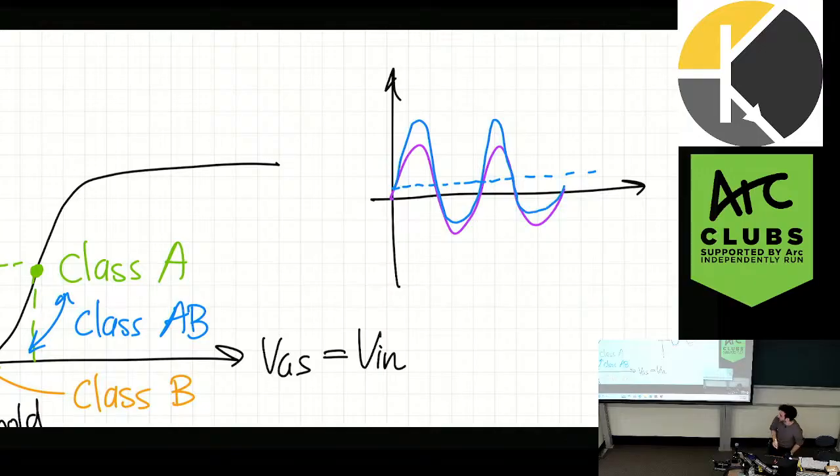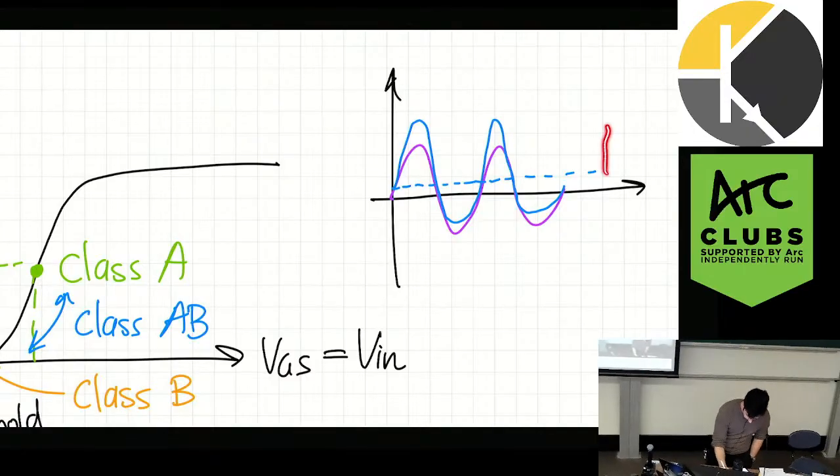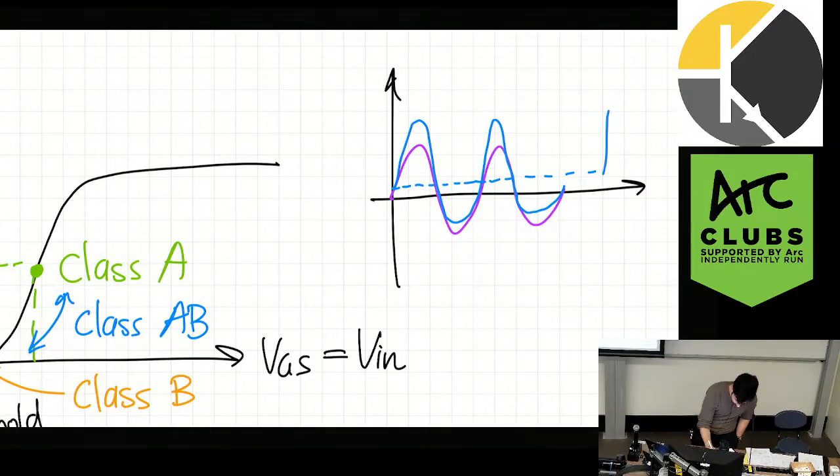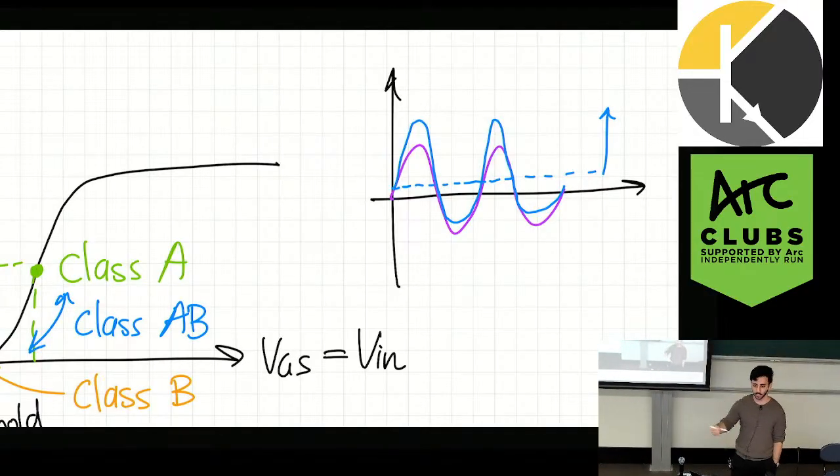So it's like it's been shifted up, right? So it spends more time on than off, right? And the more you move this bias point up, I change the class of amplifier, essentially, because I'm just changing how much current there is by default. Is that okay? Yeah. Thus far? Any questions? Now, there is class C.